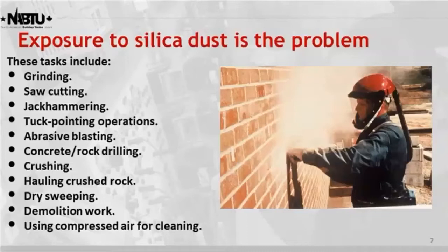The photograph here is a gentleman, actually his name is Barry Caldwell out of Local One Philadelphia. At the time he's grinding deteriorated mortar joints. He's taking an actual grinder and he's grinding out a deteriorated mortar joint within the brick, and it is a pretty dusty operation. This is considered tuck pointing. It's a process within a tuck pointing realm. Notice that he's got a full face respirator on.